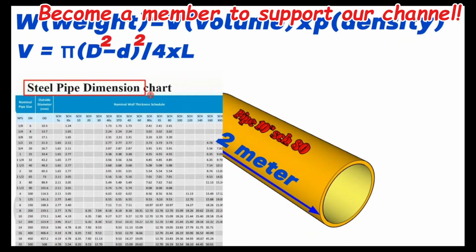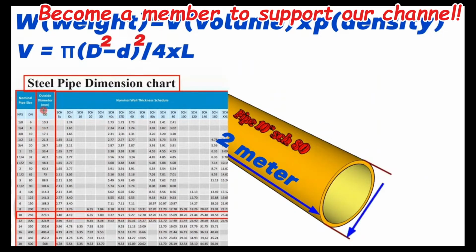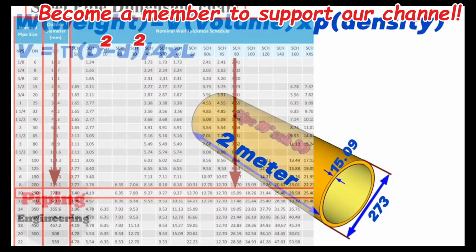This is the steel pipe dimension chart. The nominal pipe size is shown in the first column. The outside diameter of pipes is shown in the second column. The nominal wall thickness schedule is shown in the last column. We will look at the row showing nominal pipe size 10 inch. The outside diameter of the 10-inch pipe is approximately 273 millimeters and the schedule 80 wall thickness is 15.09 millimeters.